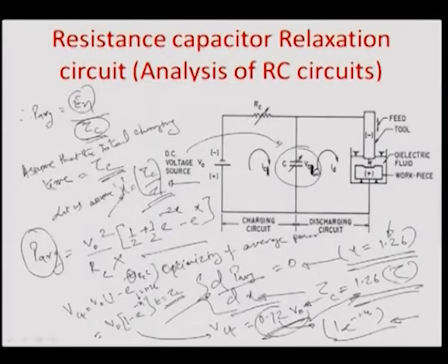So, that is about the time that you have to let the charge rise in the capacitor before the discharge would happen, and that also determines the frequency at which the capacitor should charge and discharge for optimum power delivery from the power source on one side to the discharging circuit, or the electrode discharge machining circuit, on another side. So, that is what this optimum point of 72% comes out to be.